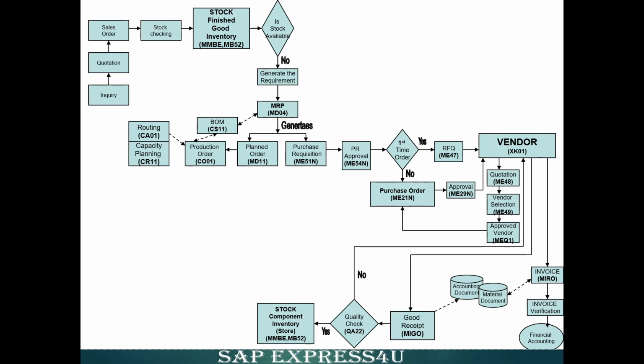Basically routing: let's say you had some process. Suppose for manufacturing this towel, you are going to do washing of raw materials, then dyeing it, then cleaning, like let's say some different XYZ processes are there. So basically you route them. You're giving a routing, the processes through which this production is going to happen.